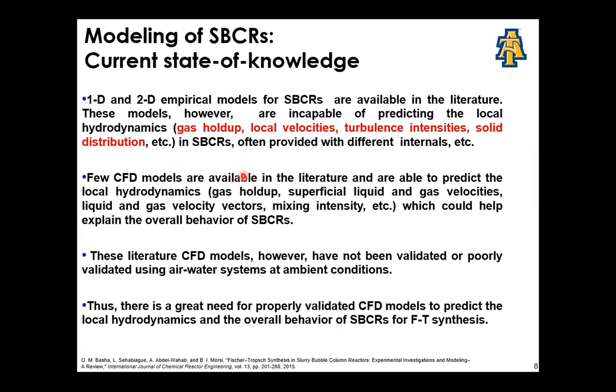Few computational fluid dynamics models are available to predict the local hydrodynamics and gas velocity, which will explain the overall behavior of the slurry bubble column reactor. These computational fluid dynamics models have not been validated using air-water systems at ambient conditions. Thus, there is a great need to properly validate our computational fluid dynamics model to predict the hydrodynamics and the overall behavior of slurry bubble column reactors for Fischer-Tropsch processes.